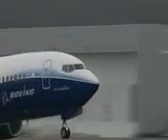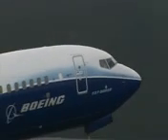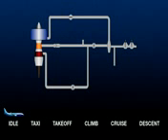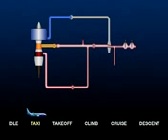Now let's see how the bleed air system operates during a typical flight. At ground idle, since the engine speed is low, the HSV is open and the system is running on 9th stage air. At these low pressures, the PRSOV is also wide open. The temperature is usually low enough that the PCCV is closed. At taxi, the high stage system continues to supply the bleed air.